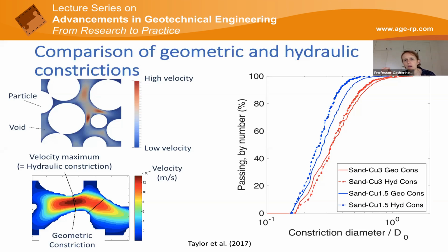And if you start to get a lot of preferential erosion of fines, you'll get a big increase in permeability. That will attract flow to that area, so the seepage flow velocity will be higher there. And then you'll start to get erosion, not just of the finer particles, but also of the coarser particles. You're just getting the material being completely eroded away, and that could lead to a collapse. And when you look at that image of Bennett Dam, where you see that there's a big hole in the dam, you can see that that's what happened there.